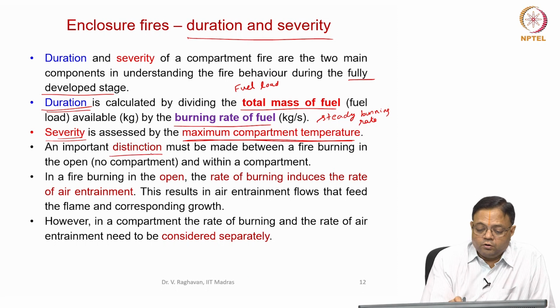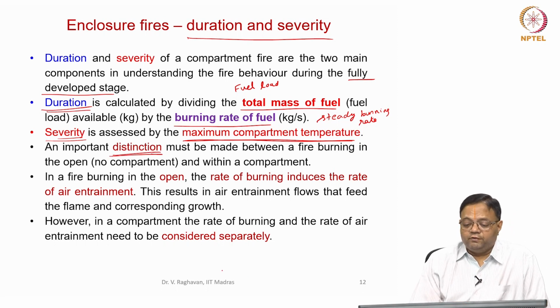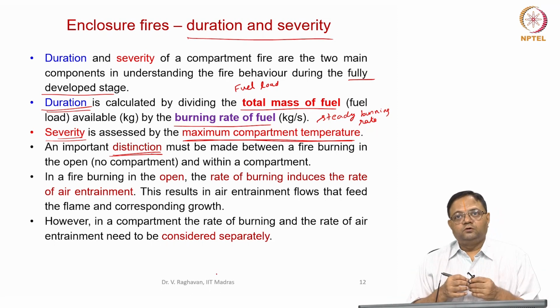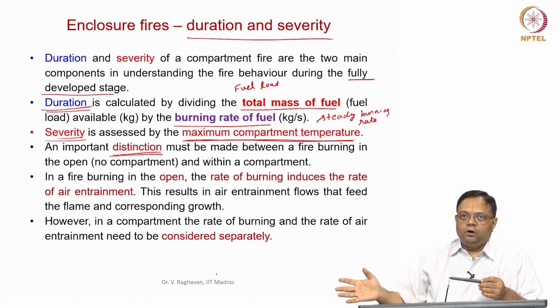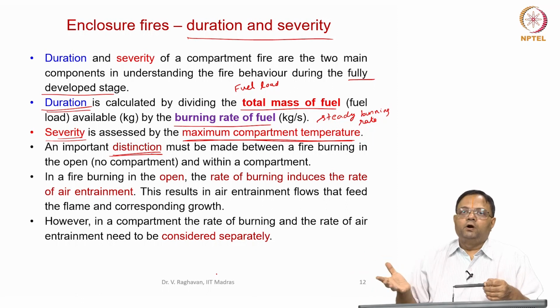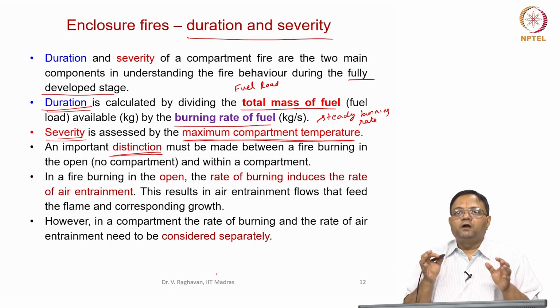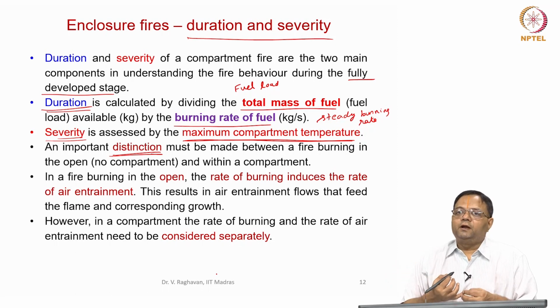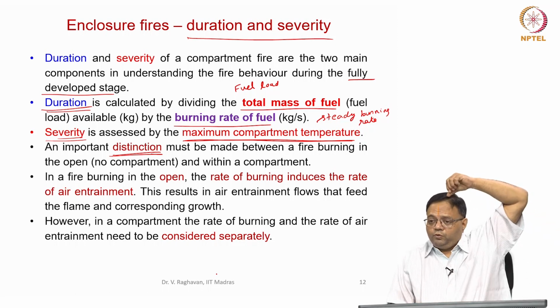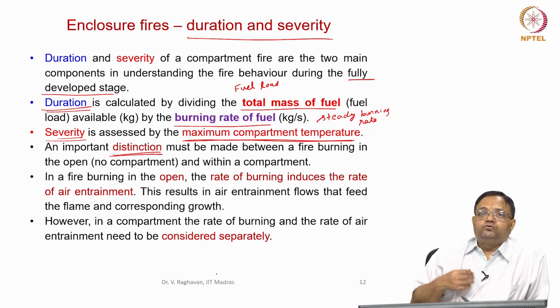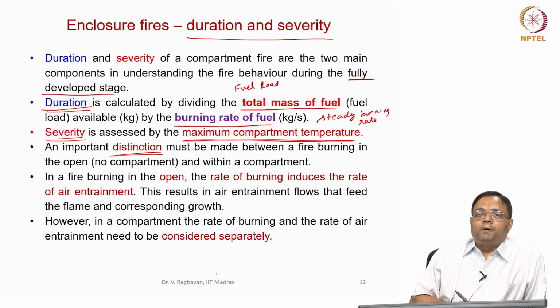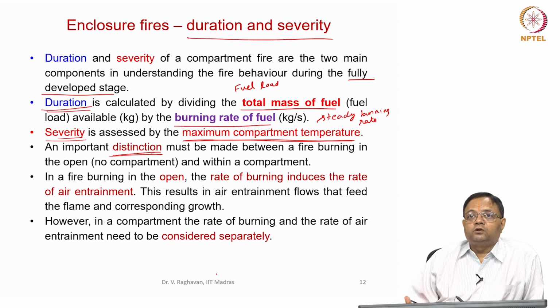Now, there is a difference between a fire in an open condition. If, for example, in an open field, I have a burning of some commodities, but the same commodity burns within a compartment, the features will be entirely different. So, the meaning of this is, when you do some tests to determine the burning rate of the fuel, the burning rate can be dependent on the enclosure effects.